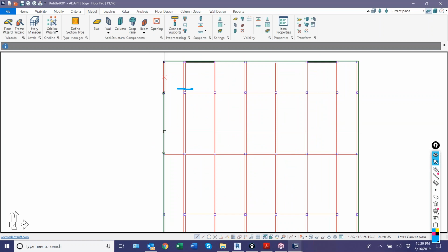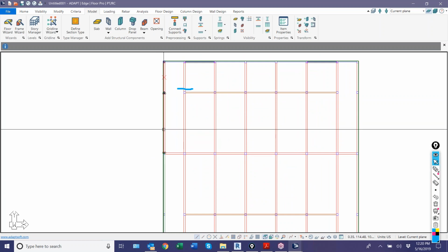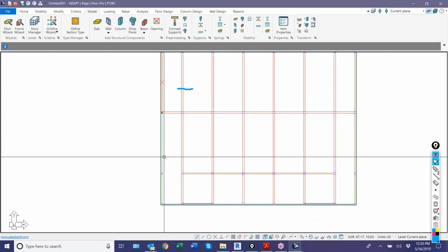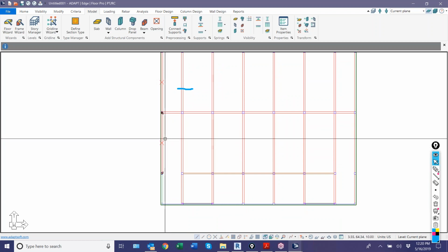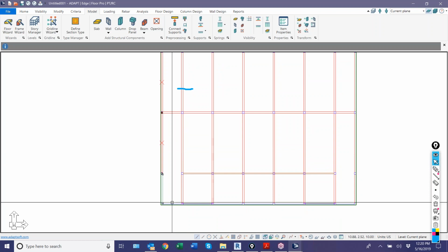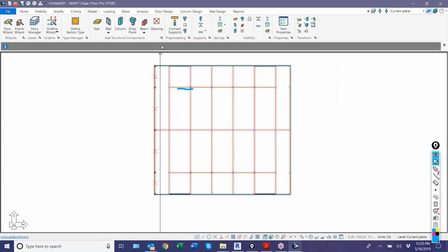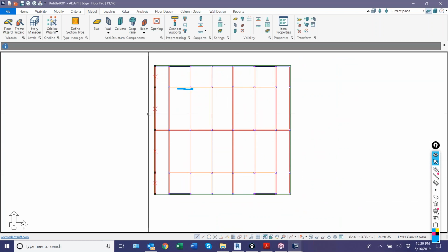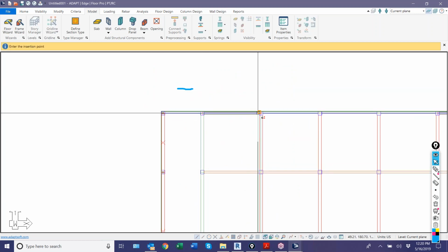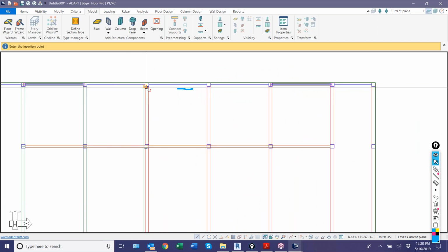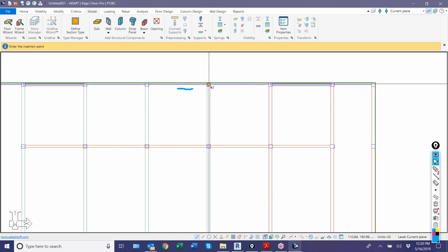We can now take this. I'm going to press Control and then Control Tab to select the other beam. The beams will show up. The structural beams are represented by this X. That means it's a structural component. So if I just press Tab, I can select those. And now we'll just use copy paste, and I can copy those to each column line, something like that.